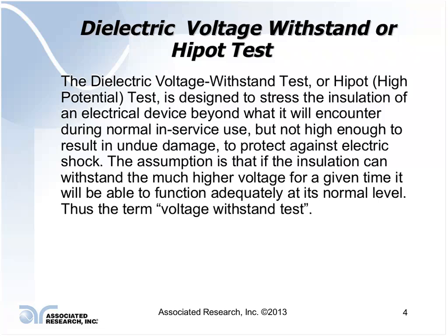The test potential is not high enough to result in undue damage, but it is there to give you a good evaluation of the insulation, to make sure it will guard against any electrical shock hazards that could exist during normal operation of the product.